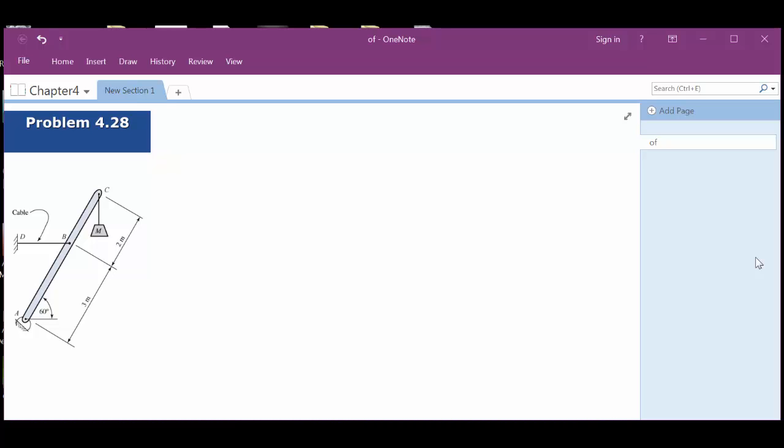Well, how about like this? It's basically a beam on an angle, isn't it? So it's just a straight line. Now we've got A down here. We see it is pinned, right? It's pinned on that angled surface, but nonetheless it's still pinned. So we're going to have an AY and an AX.